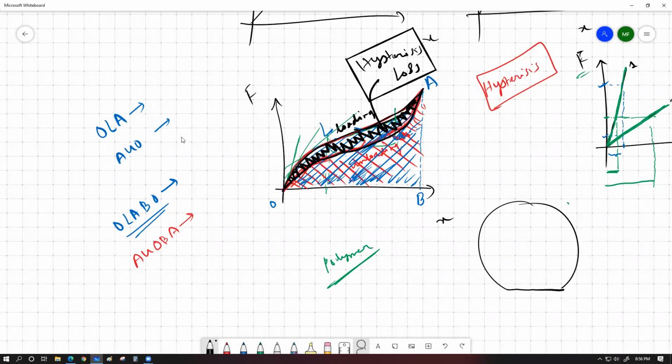Sir, the potential energy is converted to thermal, right? The faster I do loading and unloading, the more heat will be produced. Exactly. Every cycle of loading and unloading for a given specimen will produce the same amount of heat. If you produce more cycles per second, then you'll have a much higher heating rate. So how much heat you are producing in terms of power depends upon how many cycles you are performing per second.